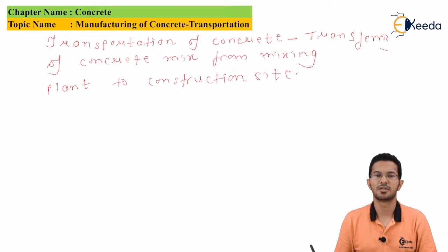There are many elements of transporting that need to be considered in order to ensure that a mix does not change its state as specified in the contract. The two key goals when transporting concrete from the mixing plant to the construction site are to prevent segregation and to not reduce the workability of the mix. This transportation process must be well thought out and organized efficiently.